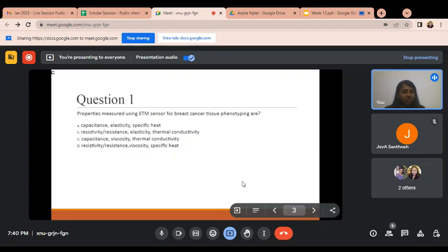It means positive photoresist, when coming into contact with the UV ray, and after that we dip the wafer into the developing solution, it will go out. But if the negative photoresist comes into direct contact with the UV rays, it becomes harder, so it will stay. And which portion is the chromium, the mask, so which portion is covered with that